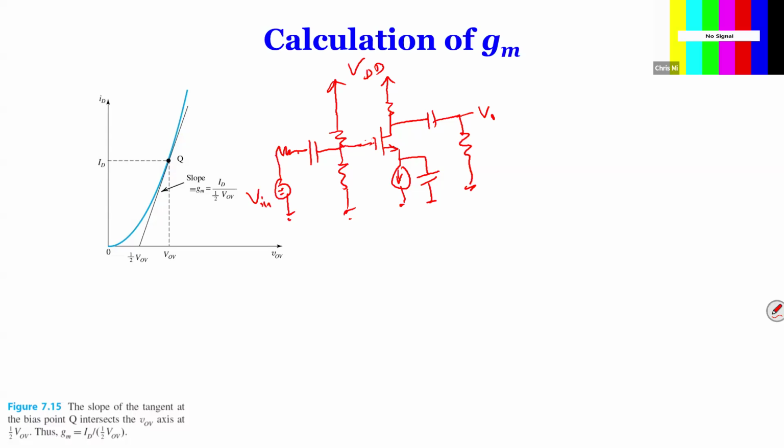Okay. So what we're doing here is we try to find the equivalent circuit so that we can later solve the problem. But first of all, I added a couple of capacitors, and this is what we call bypass capacitors. And secondly, I added a current source.